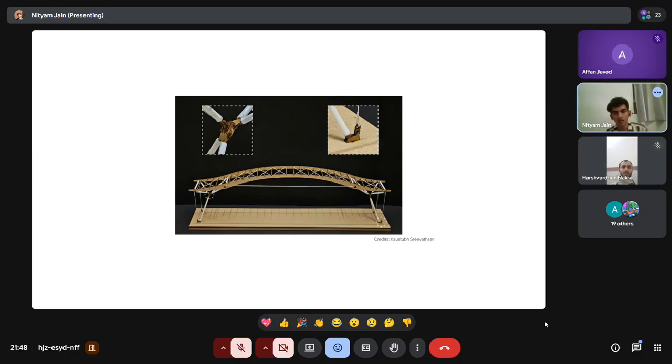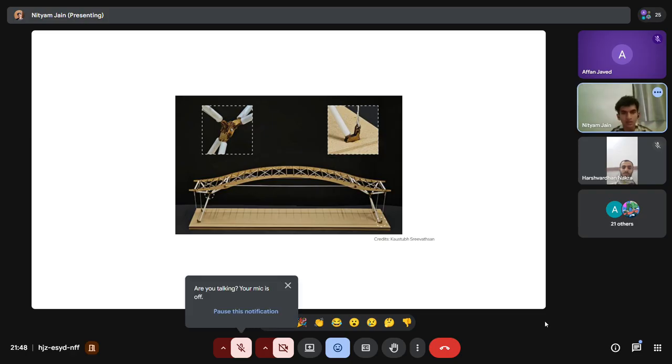Because the board and the material is so thin and flimsy, when you put the gravitational load or the lateral loads, or give it jerks like the earthquake load, you should be able to see the deformation it's going through, where the bending is happening, where tension is there, the threads might get tighter or they might get looser. So you understand what failure might happen to the building on these kind of loads. So maybe it will help you understand the building or understand the specific role of each part of the building.